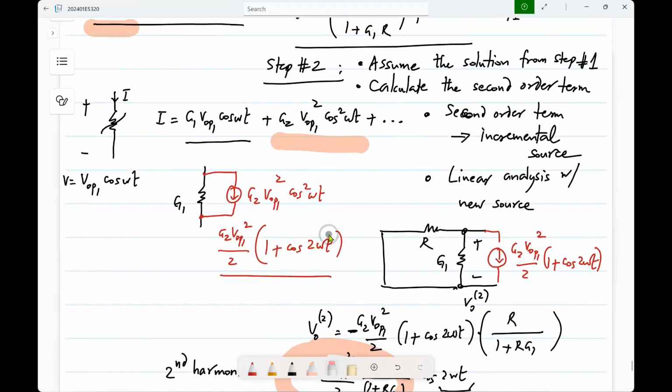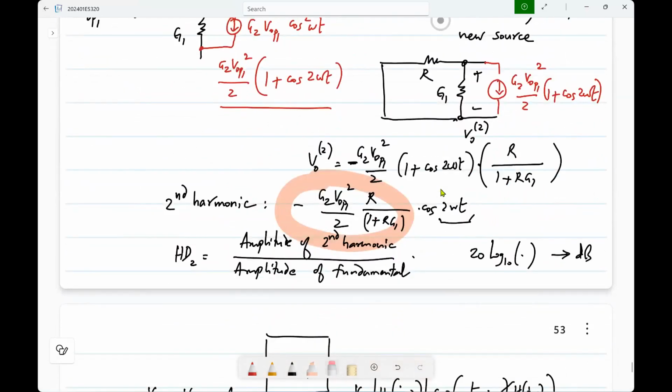What happens is when you pass it through a nonlinearity, you calculate the first order term, the fundamental component, using the small linear equivalent circuit. You will get some amplitude. But higher order nonlinearities can also give you the fundamental term. And that correction is what usually comes out as compression, okay, or sometimes expansion. So that's what it is. So you can go on refining it, but what we have done is at least we only calculated what is qualitatively new. If you calculate only using the small signal linear equivalent circuit, you will say that, oh, this has only sinusoids at omega. Now we need to know the sinusoid at 2 omega, that we calculate at the first step.